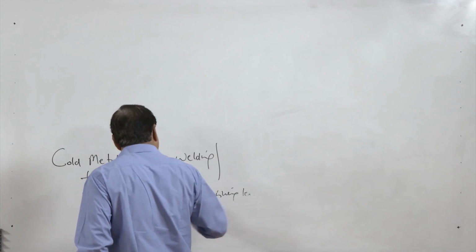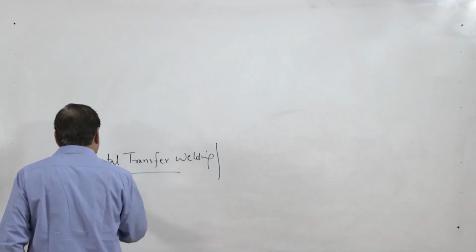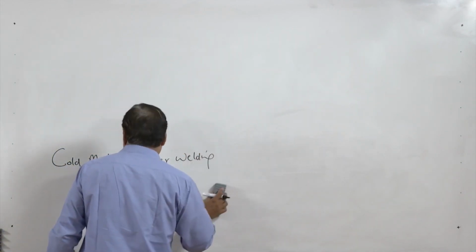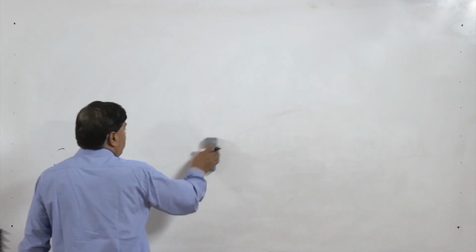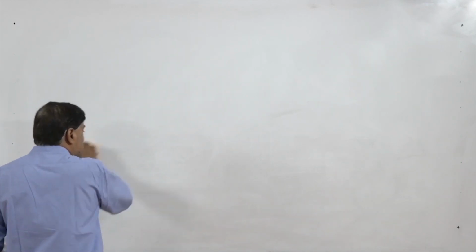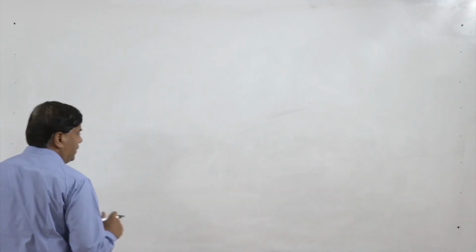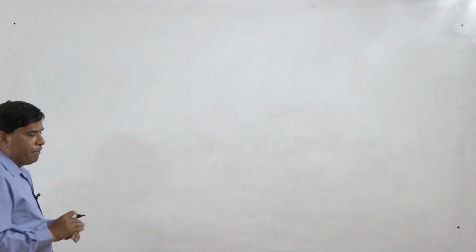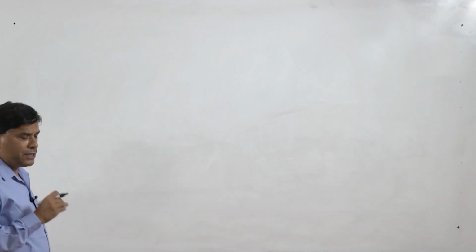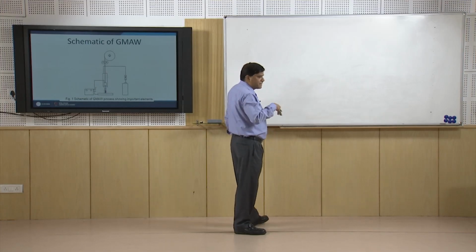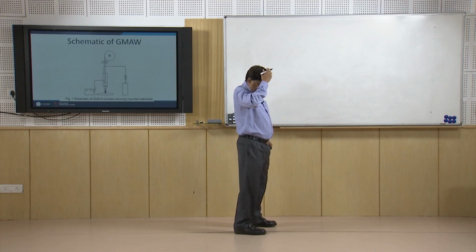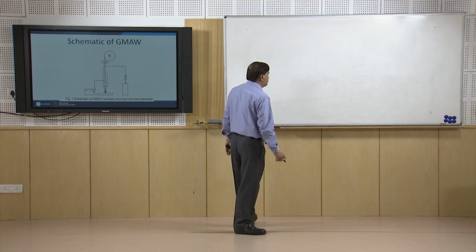The heat generated and the current conditions used for this kind of transfer or this kind of welding process are very low as compared to the other processes. That is why it is called cold transfer. But this process also combines some benefits of another variant of GMAW.